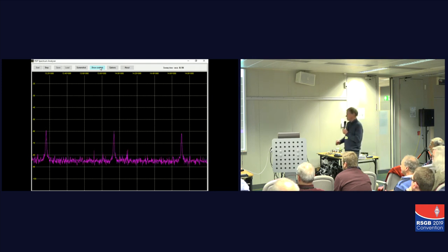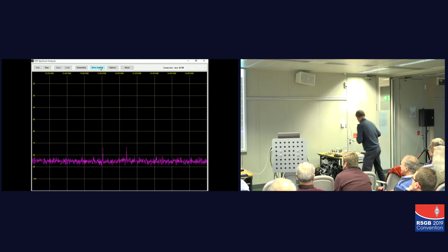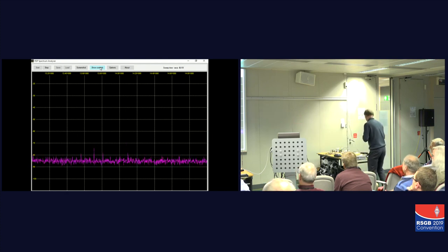It puts up a big signal, quite narrow band, in the 14 meg amateur band. For some reason it's shutting down, possibly because it's decided it hasn't got a speaker connected or something like that. I'm also rotating this to try and peak it. Yeah, you might be best to turn it 90 degrees from where it is now. You might be on a null there.